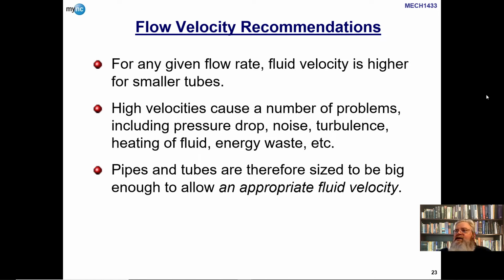Now what you need to consider is the pressure that's going to be inside the pipe, and make sure that you choose a pipe whose inside flow area is enough to carry the flow and whose wall thickness is enough to support the pressure without bursting. We're going to mostly pay attention to the first part, the size based on flow rates. And it's fairly intuitive, I think. There's nothing very counterintuitive about it.